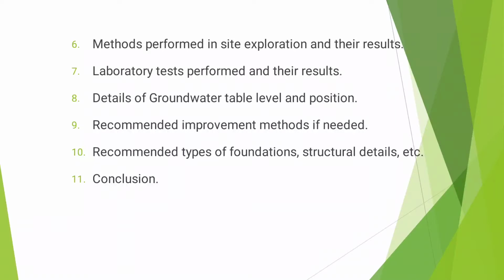By conducting the tests we can know the location of groundwater, so we write in detail about the groundwater level and its position. Next, any recommended improvement method if needed in that area, or recommended type of foundation, such as structural details, etc., are to be mentioned. And finally, the conclusion of the investigations and of that area.